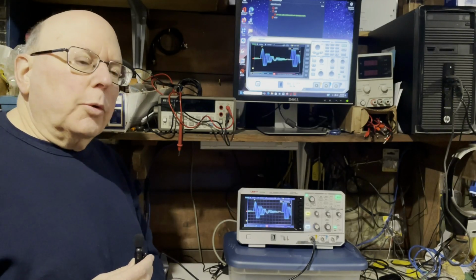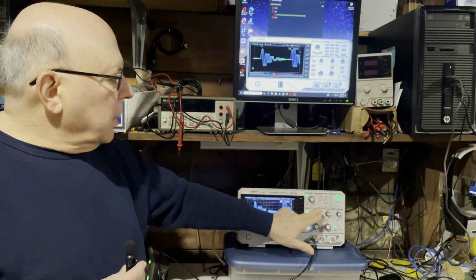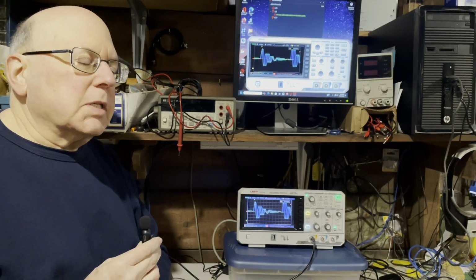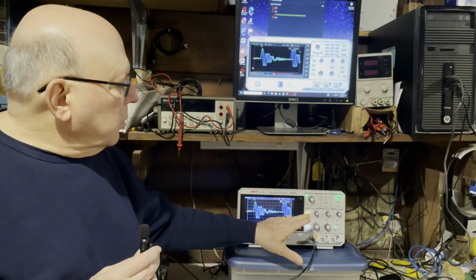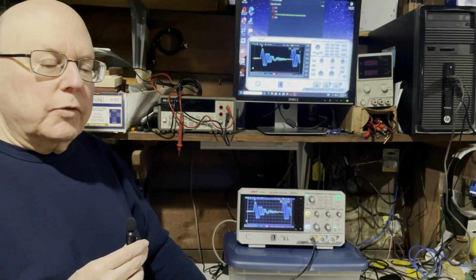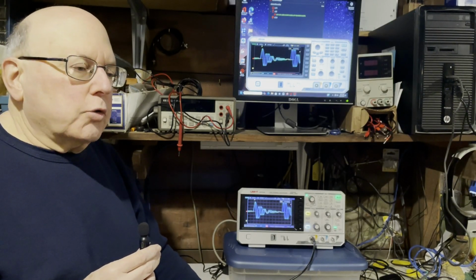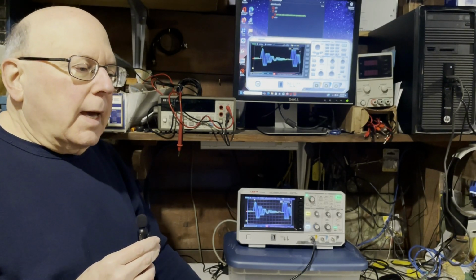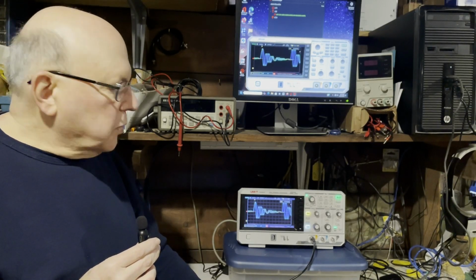The 4-channel scope will do all of the same things, just has 4 channels. So for example, you've got math, trigonometric functions, things like that. You also get an FFT. You also get various forms of analog and digital triggering, including logic triggering and bus triggering and an nth edge trigger, which we found very useful.